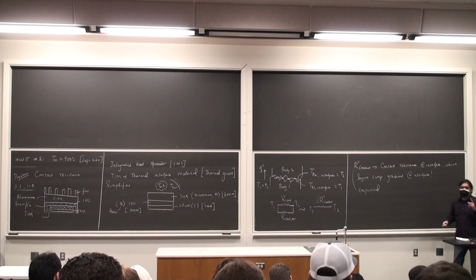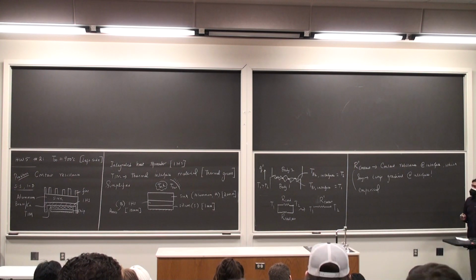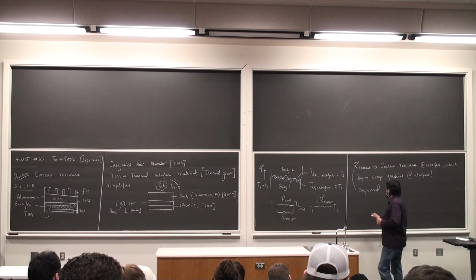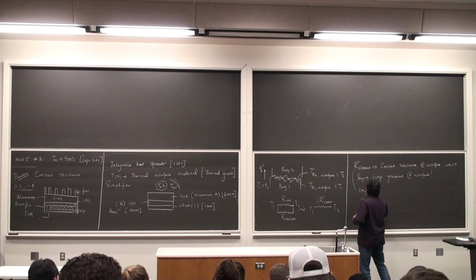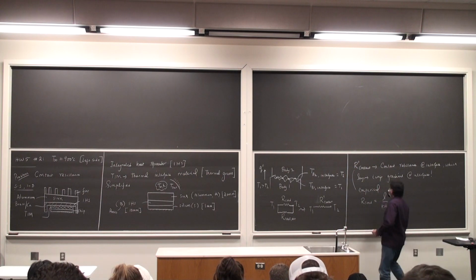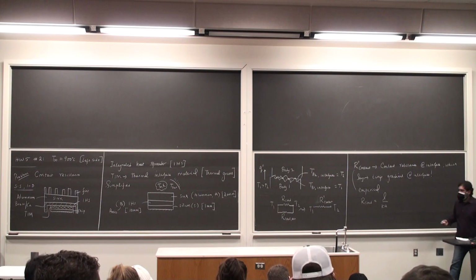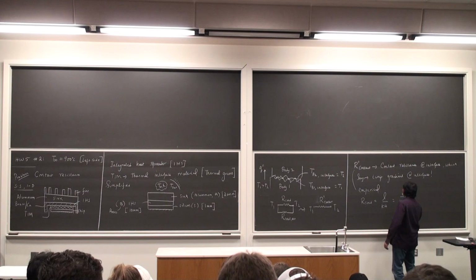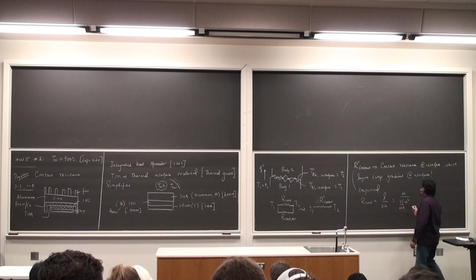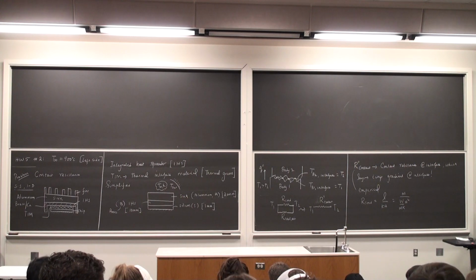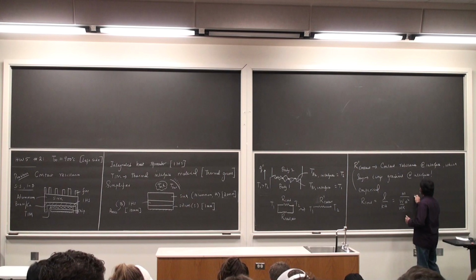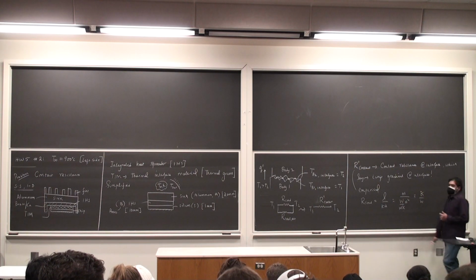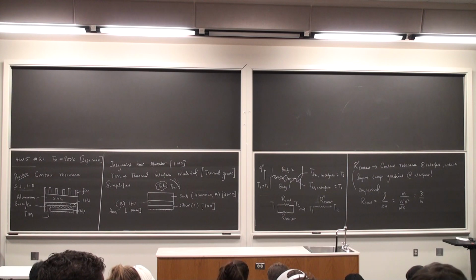And very important is the following. When we spoke last time, I did not mention the units for thermal resistance to conduction and resistance to convection. Let's take a look at it. So our R conduction is L by K times A. And if you look at the units, let's say SI system. So this is meters, watts per meter Kelvin, and then this is meter square. And you do the simplification, you'll end up getting this to be Kelvin per watt. Okay, this will be the units for thermal resistance.